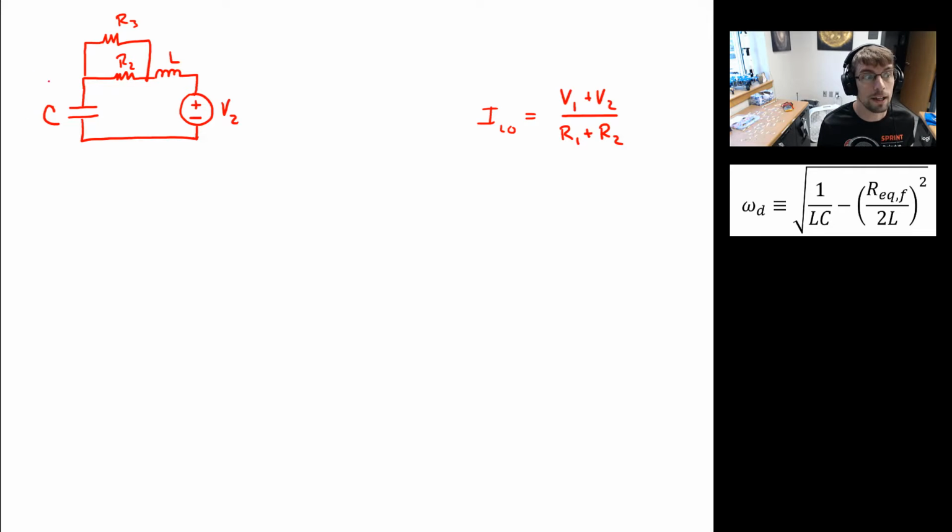So let's go ahead and think about for a minute again. We know that the potential across the capacitor, node A if you prefer, is related, and I'll use the dot, to the capacitor current divided by the capacitance. Okay. Remember, we're taking our general equation for the potential drop across the capacitor, and we're just taking a time derivative. Okay? Good.